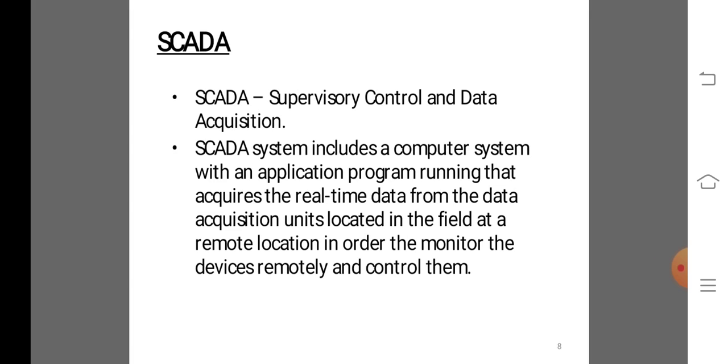Then, the functions of a SCADA system. It contains 12 functions: data acquisition, information display, supervisory control, that means on and off, generator stop and start, raise or lower commands. Fourth is information storage and result display. Fifth, sequence of events acquisition. Remote terminal unit processing, general maintenance, runtime status verification, economic modeling, remote start-stop, load matching based on economics, load shedding.